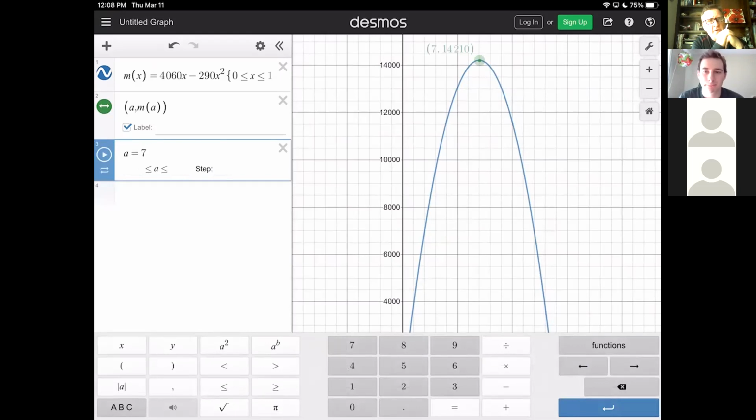So the place where we needed no beam for shear, we need way more beam for moment. So it's actually the maximum shear and the maximum moment that we got to look up in that table I showed you. Otherwise, the beam's going to break. You can't just pick the moment at any location you want.